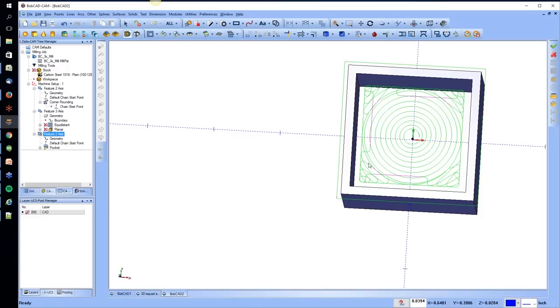Now, that's covering your 2D pocket options, right? Obviously, with pocket, there's a lot more options with zigzag and everything. So zigzag is just a back and forth, okay? Hopefully, this is giving you guys some more insight into go in and play with some of those toolpaths. Go in and actually see what the output is, because sometimes you're going to be able to find something that's actually going to work better, maybe for your particulars of what you guys do. If you do specialty parts, you might find a toolpath that saves you more time. But actually use those different options.